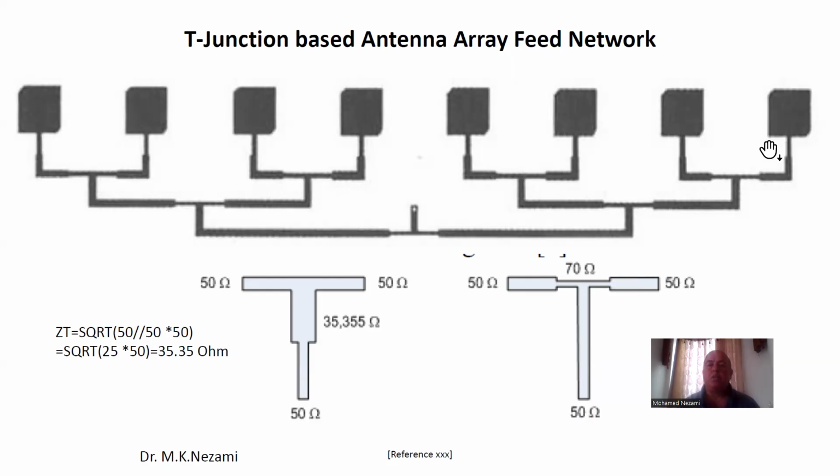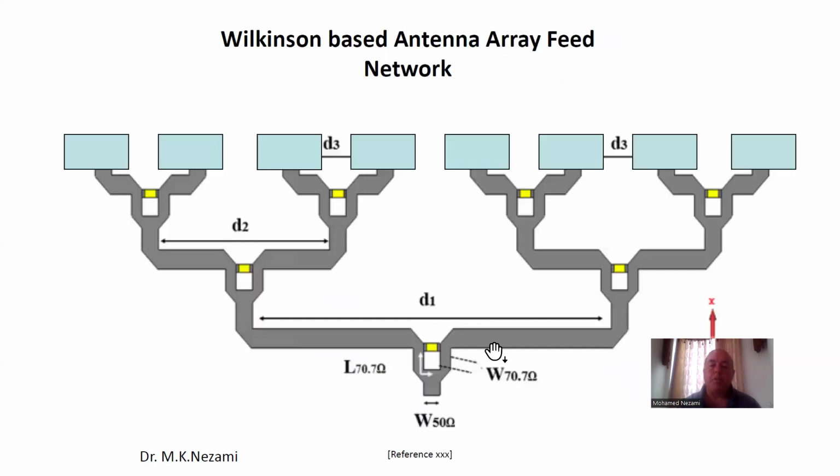So when you design this, you're given a set of antennas that are spaced, and you know the locations of these. Therefore, you need to start designing with these transformers and extending half wavelength lines until you build up so that you have the signal arriving with equal phase shift and delay at every one of those elements. So that's why it's not really a trivial thing.